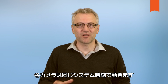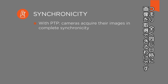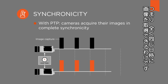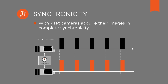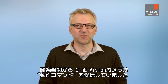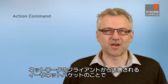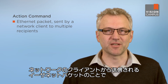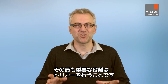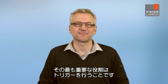Thanks to PTP, all cameras are working with the same system time. This means that all the individual cameras capture each image at the exact same time. Since the earliest stages in their development, GigE Vision cameras have been able to receive and react to what is known as action commands. An action command is an Ethernet packet that can be sent by a network client to multiple recipients on a network. The most important use case for the action command is triggering an image over the network.